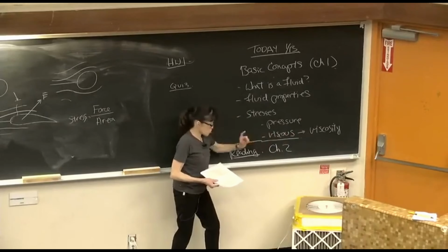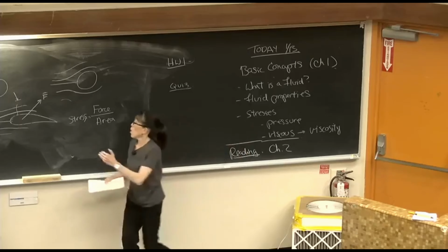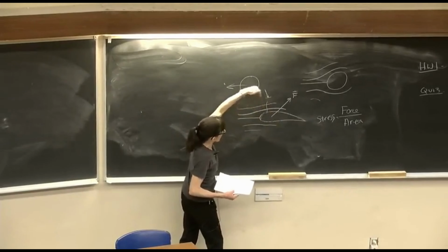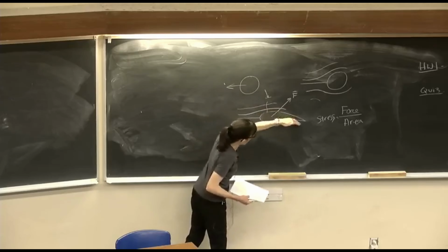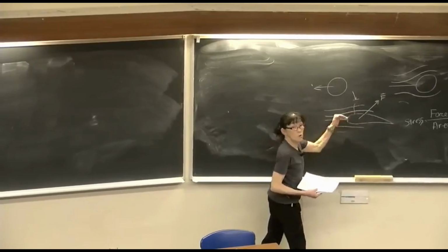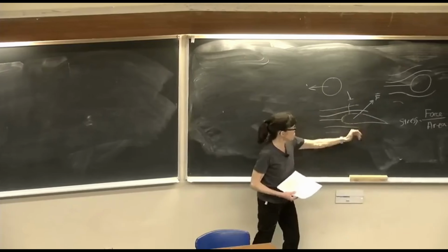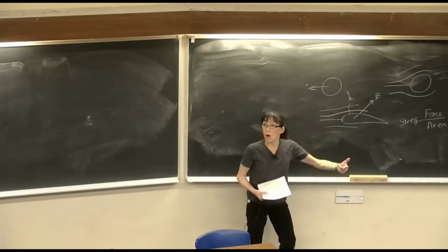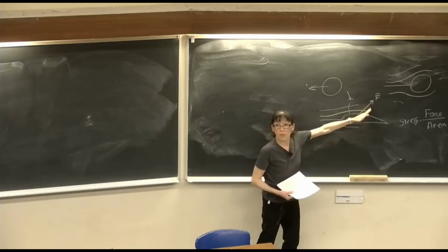But more generally, we consider it as a viscous stress, force per unit area. So along with pressure contributing as a force, and pressure will result in a normal force, there will be a tangential force also along the surface. And that tangential or shear force, if you know the distribution, can be integrated over the entire area to get the associated shear force and its contribution to the net resultant force.